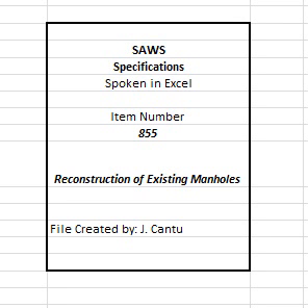855.5 Construction. Manholes shall be raised or lowered by replacing the existing cone and manhole section or sections as required for installation to the finished surface course. 1. All openings shall be protected by hatch covers or the necessary steel plates. 2. The contractor shall be required to backfill all manholes to 1 foot above the top of the cone section to allow for the concrete ring encasement.